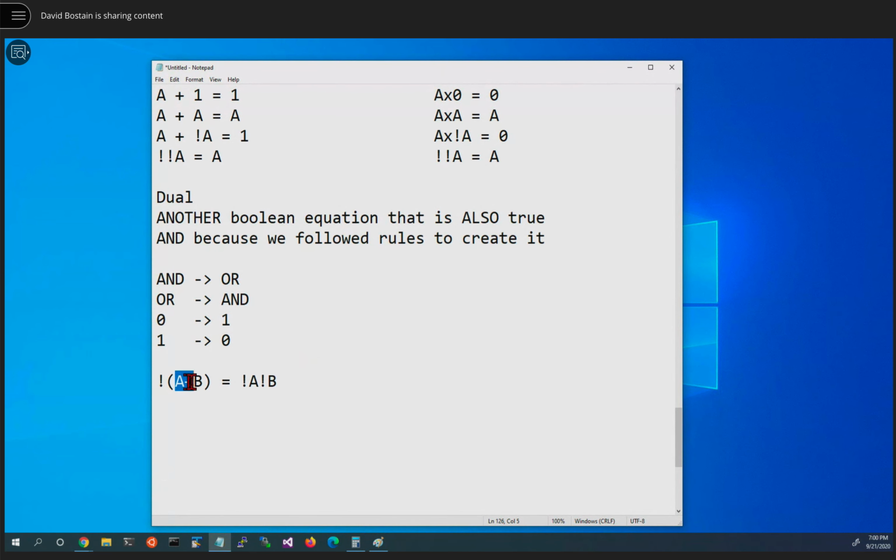This says we're going to do the function and then invert it on the way out. This says we're going to invert the variables on the way in. If I wrote the truth tables out for these, you'd see they are identical. The name of this function is a NOR function, not OR, meaning that it's going to do an OR and then reverse all of the output.